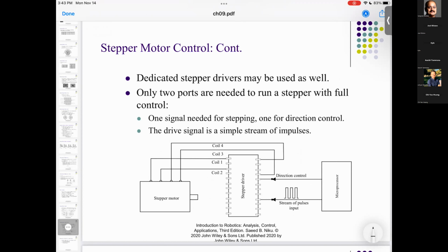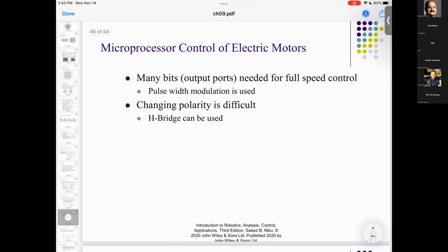And this is how a stepper driver looks. If you look at the stepper driver, it's just an internal IC chip, an integrated circuit. All the ASIC is internal. Usually they have some type of heat sink that can dissipate the heat because of continuous on and off, on and off. But you have a microprocessor or a microcontroller that is sending some type of PWM, and you can flip certain pins on and off that will change the direction of the stepping.